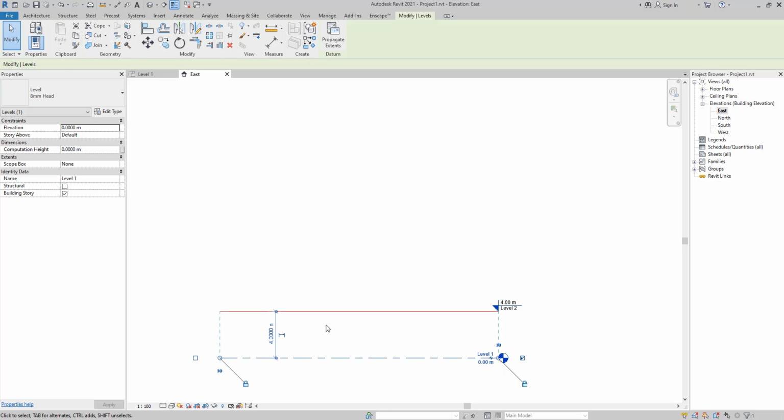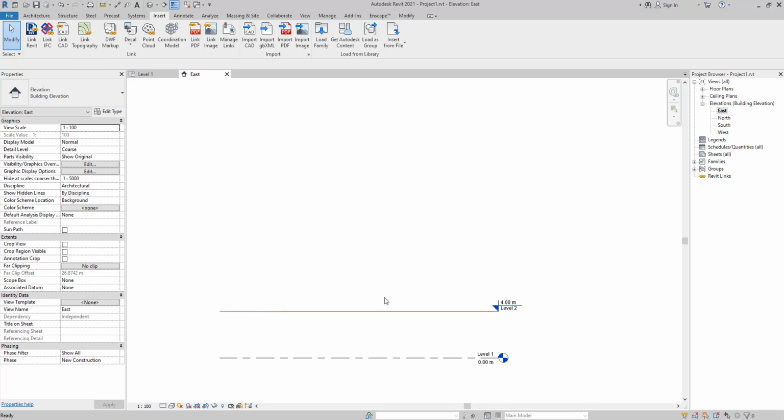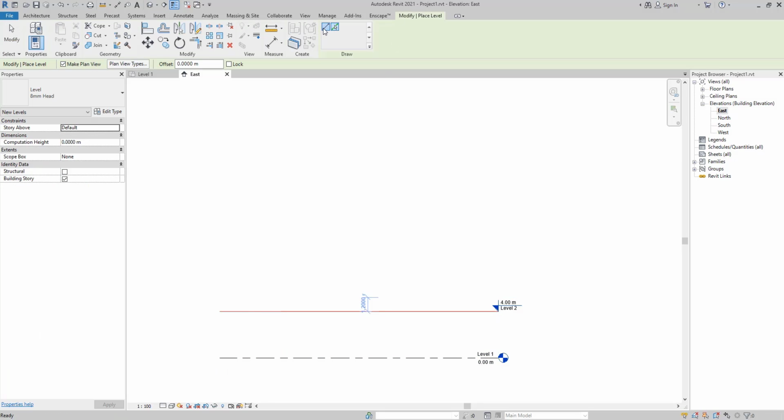So you created your own level, and after that, for creating level, you are going to create your level by going to properties and choose your level option here. If you could do this, you don't need to use any kind of options so far, because you already as a default going to choose your own creation.